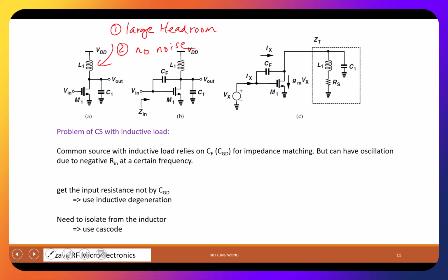When you're doing your cascade, remember you kind of decouple it. You do your input design, and then the output design separately, output impedance and input impedance, right? You no need to worry that now I match the input impedance and later I try to change the loading to reduce the gain of my LNA, then it's going to affect my input impedance. That can kind of decouple. This one is fully, heavily coupled, right?